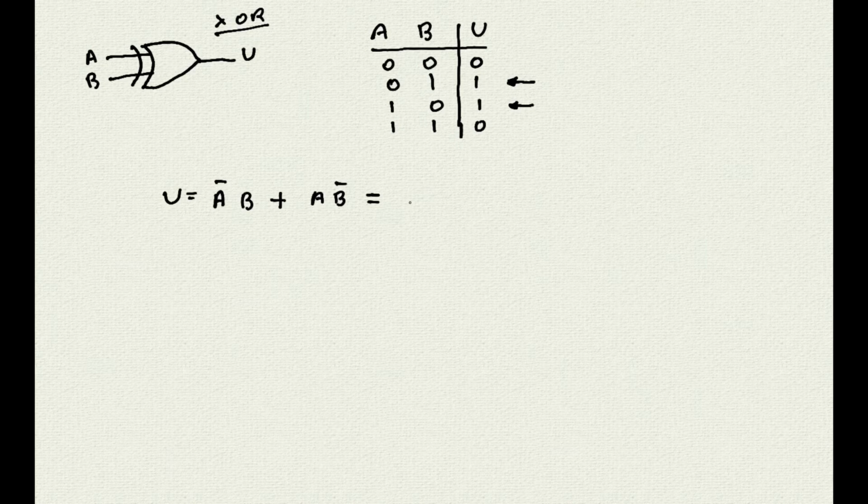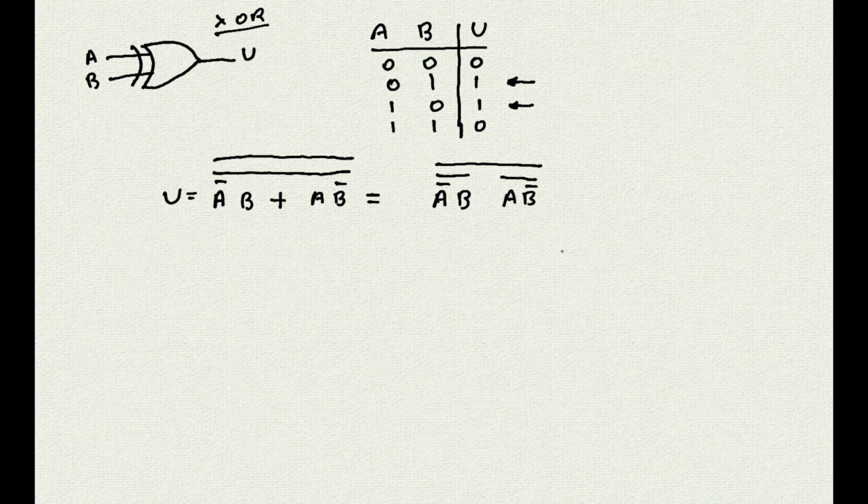We can put two NOT symbols on top of the whole expression, which does not change the results, and then we can associate one of these NOTs with the OR symbol, making it a NOR. Then we can apply the DeMorgan Theorem like this. And now the expression is all in terms of ANDs and NANDs, which we can represent solely with NAND gates.